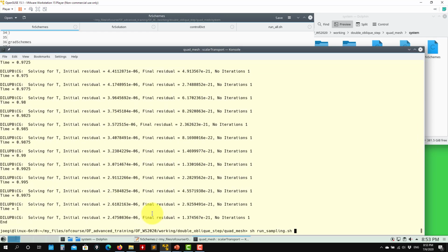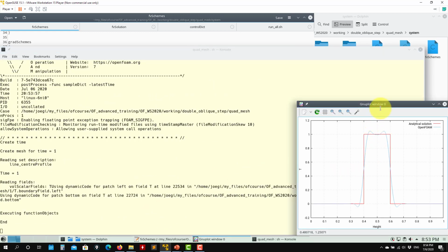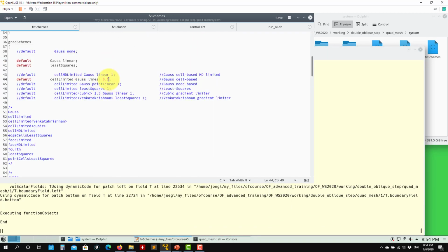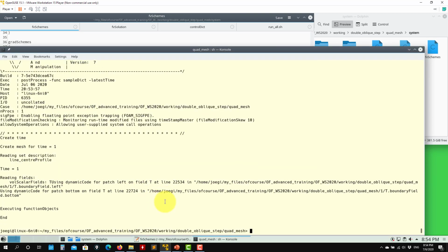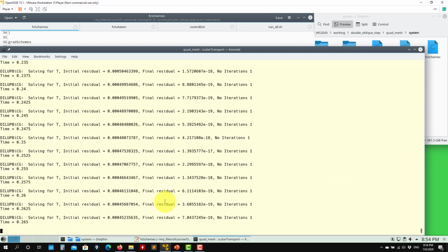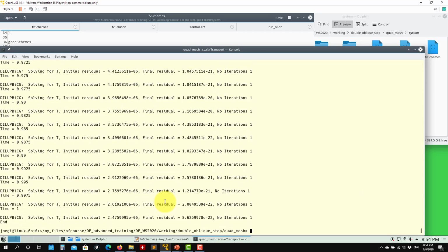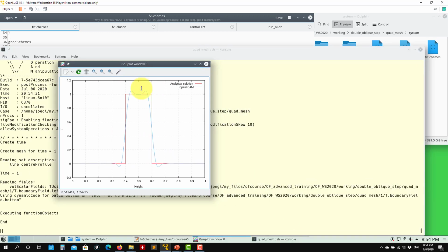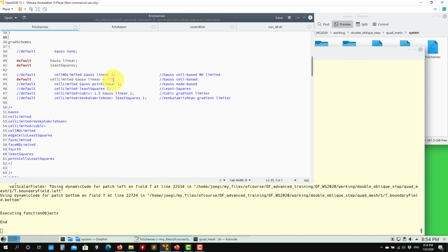So that is the quantity that you are limiting. So see that 0.5 is not okay. This is important because there are some quantities that you don't want to limit too much. For instance, if you're doing aerodynamic computations, probably it's not a good idea to limit pressure too much because it can have an influence on your forces. So usually in pressure, you try to avoid adding a very aggressive limiter. And also, for instance, in multi-phase flows, you have the curvature of the interface. Also, you don't want to limit that quantity too much. But for velocity, it's recommended to be aggressive and limit that one.